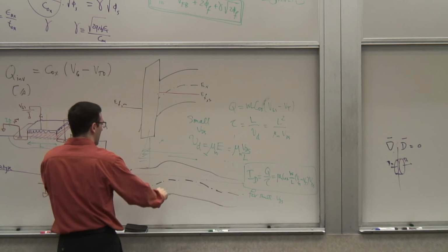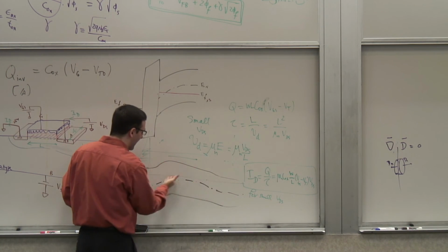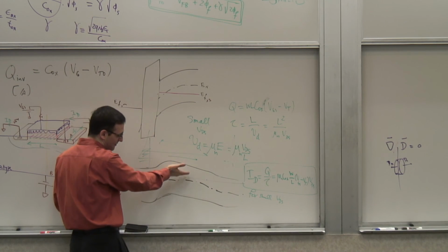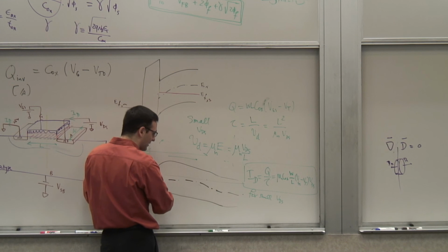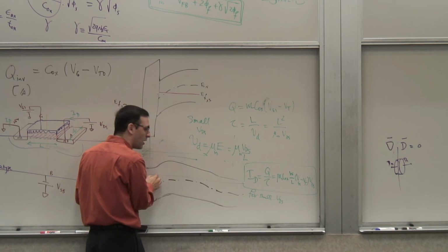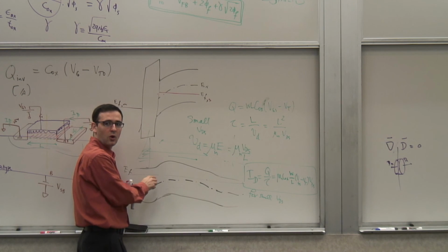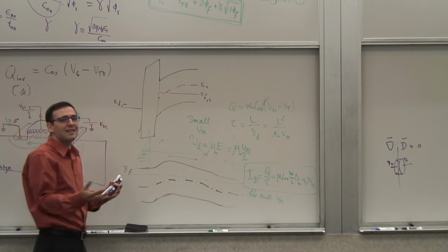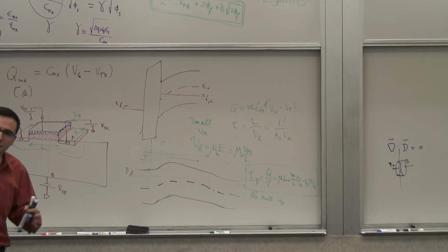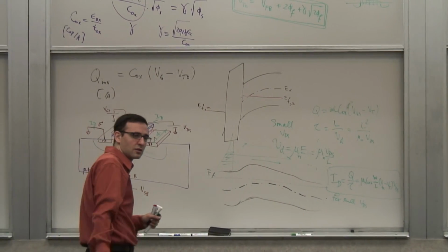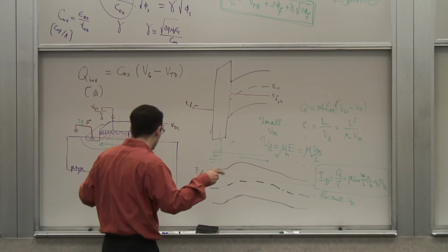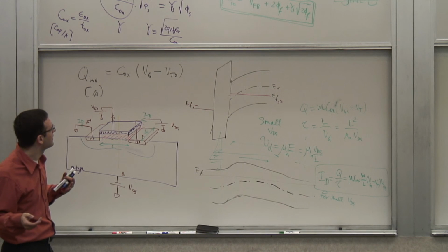It's a drift device. What you've done, you've created an N-type region, albeit with different numbers of electrons at different points, but nonetheless they always have electrons as majority carriers. They never become minority carriers. They're always a majority, and therefore there's plenty of them. So when you apply an electric field, you create a net flow in one direction or another due to the drift, on top of the very large thermal movements of the electrons that you already have.